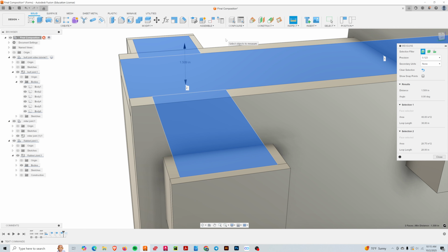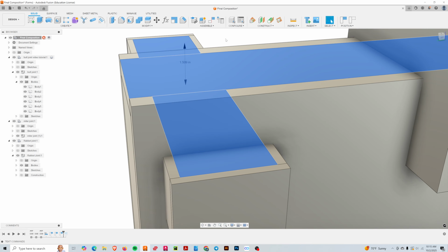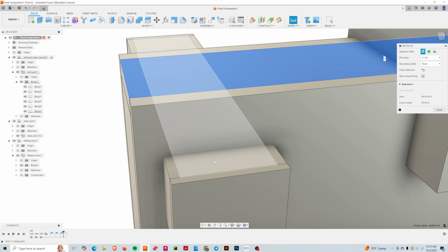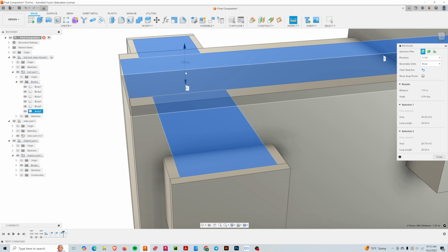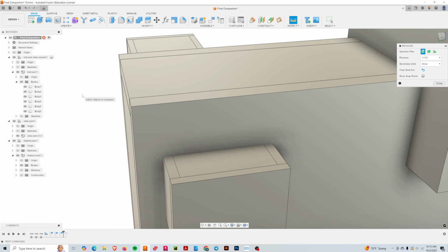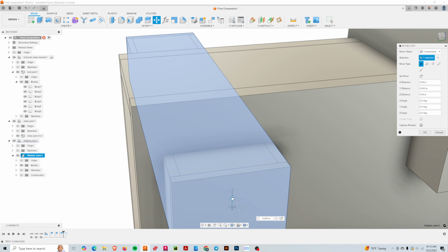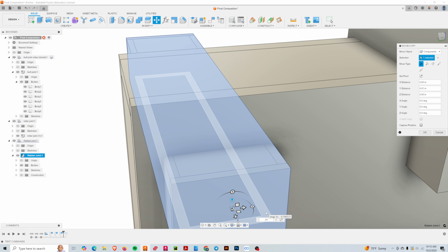Okay. That means I went the wrong way. I need to add, not subtract. So I'm going to go back, or you can press revert position and let's see where it is now. Okay, so it means I have to go up 0.01, not a thousandth of an inch. Okay, let's move this up 0.01.